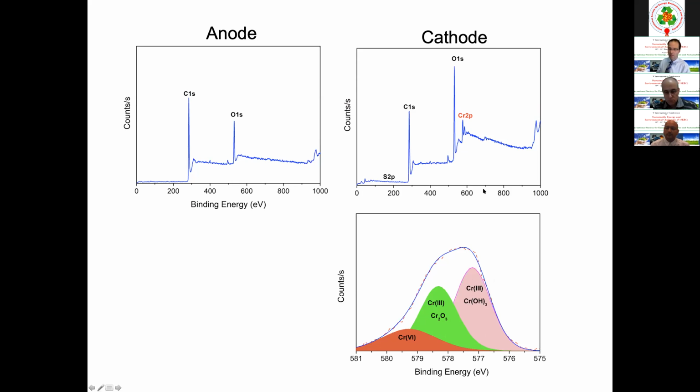So when we use the flow-through method with the same system, we see that the removal is much less. However, if you put membrane stacks, so stacking multiple membranes, you can increase the removal of chromium, and the retention time is very important. So if there's ways to increase the retention time of the pollutant within the membrane, then you can get a higher removal.